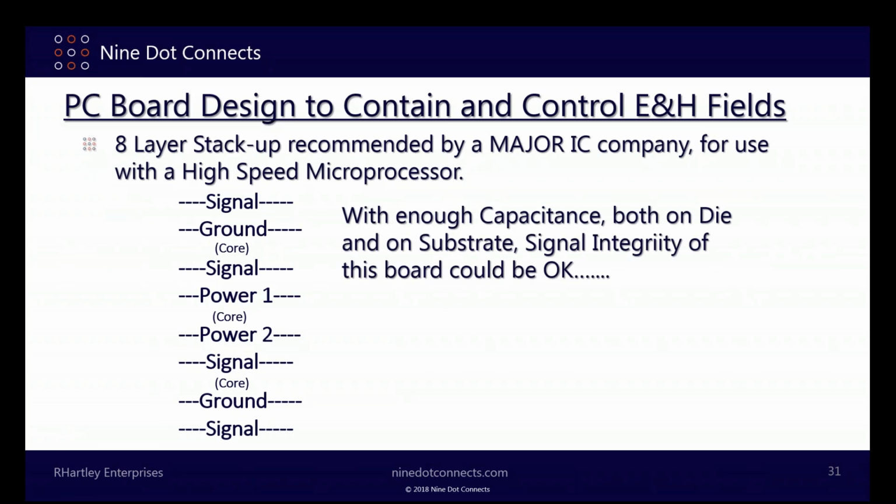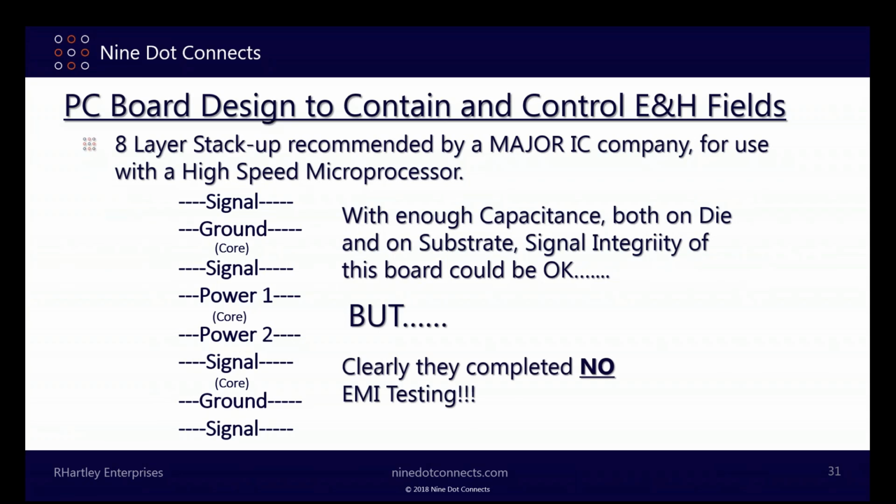I can believe with enough on-die and on-package capacitance that they were able to make this thing work, because the power delivery is far less than ideal here. But if they put enough capacitance in the package, I can imagine they got this thing to function and have good signal integrity. What I can't believe and won't believe is that they did any EMI testing. There is not a chance in Hades that this board could pass EMI testing.